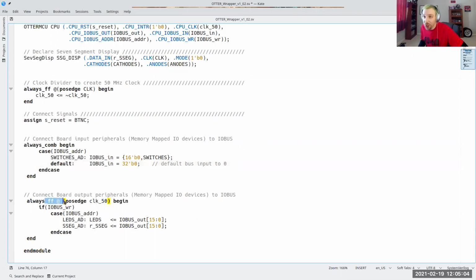If it's sequential logic, you're defining flip-flops. Flip-flops are fine, right? Flip-flops are memory. And so having an undefined option, a non-default case, right? That is your save state. That is don't change anything. Well, flip-flops don't change, right? That's fine. That is what they're designed for. So having that save state fits within a sequential block.